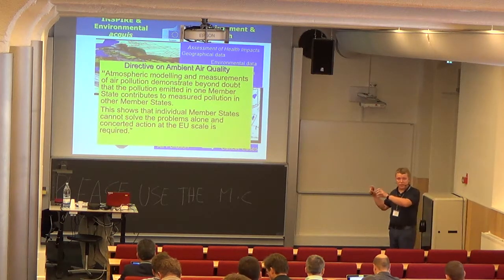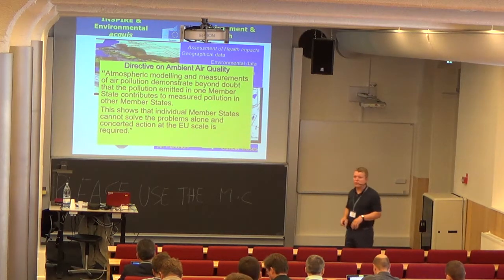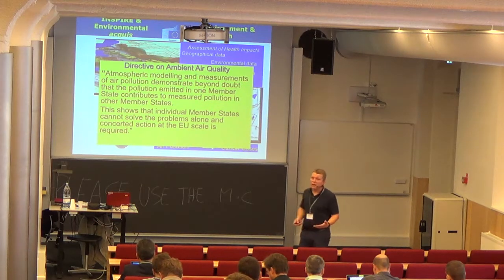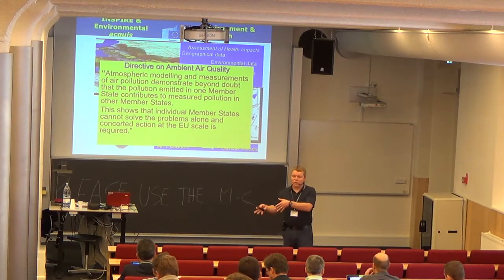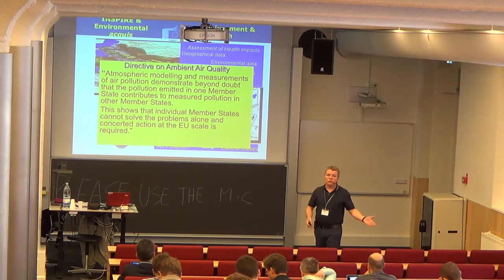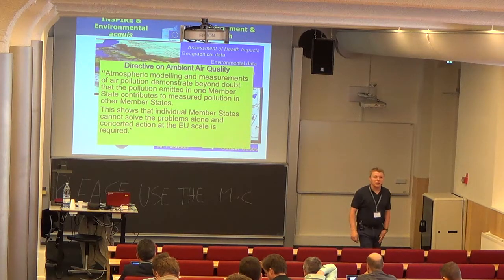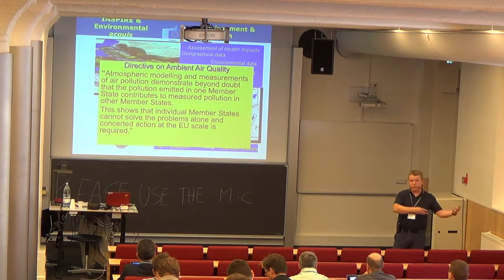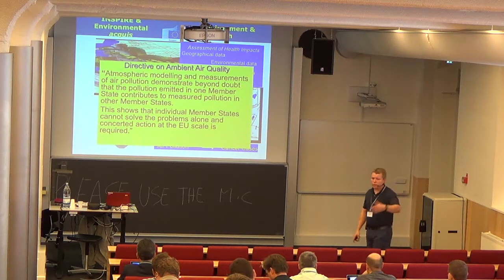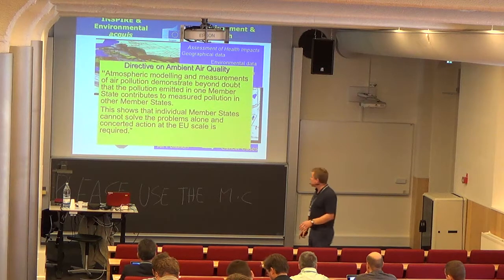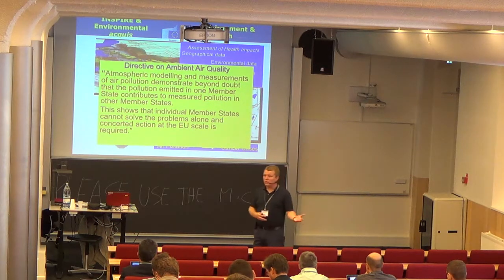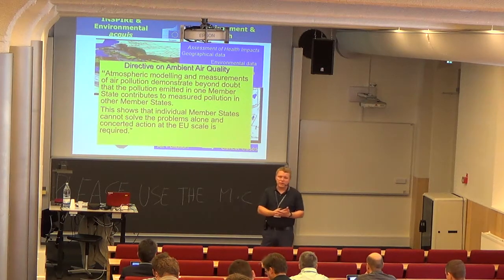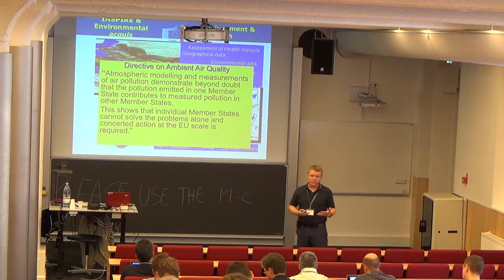That's why the first data team of the Inspire is actually about coordinate reference systems, which says, okay, if you really want to share your data, you need to use the European Terrestrial Reference System 89, and then you will be able, of course, with the proposed Transverse Mercator projection, to really combine your data, to overlap the data between countries, and to use the data.